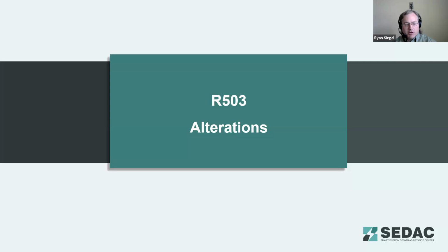We did have a question come in regarding adding insulation to a wall that is common to an existing building, and the existing common wall changing more than 60% of its original design. Will that common wall be required to meet the new code? For that, the important thing is understanding where it is part of the building envelope. So it may be such that when you put an addition on, a portion of the wall that used to be part of the building envelope, due to the addition, no longer is part of the building envelope, and that building envelope now comes across the addition as well.